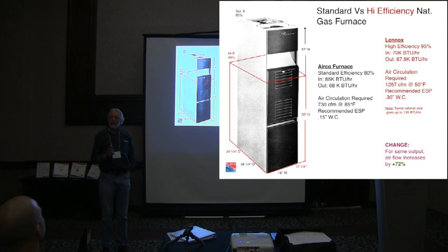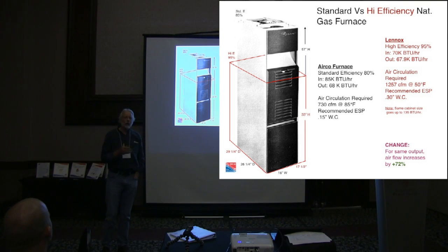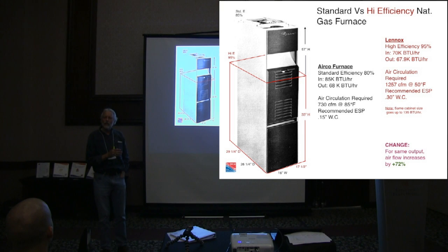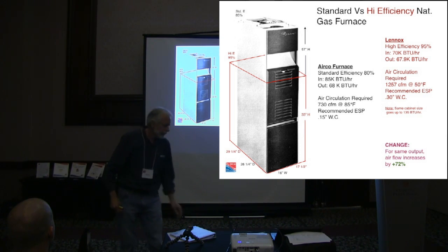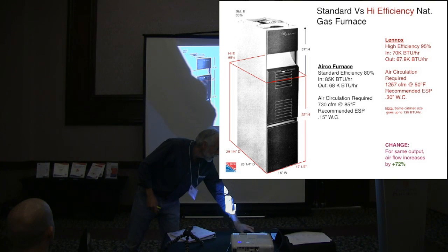The bottom line with heating equipment, you have to scrub more air across these devices to get them to be more efficient. There's no other rules to do it. The more air you put through that furnace, the more heat you're extracting from that heat exchanger with only the smaller residual going up the chimney. Really, really simple. You can't argue with this. It's physics.